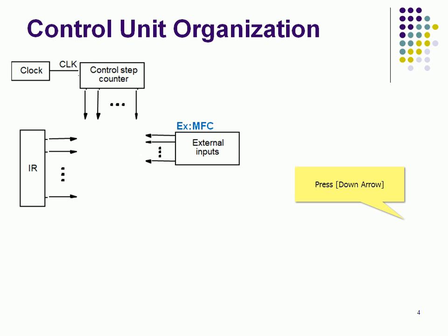And for example, as I told, interrupts, MFC, and also the condition codes. Condition codes are majorly flags. After every arithmetic and logic operation, the results are going to be reflected in some of the flags. For example, flags may be the carry flag, auxiliary carry flag, Z flag, that is the zero flag, sign flag, and P parity flag. Several flags like that will be there. Those flags also contribute to deriving the control signals.